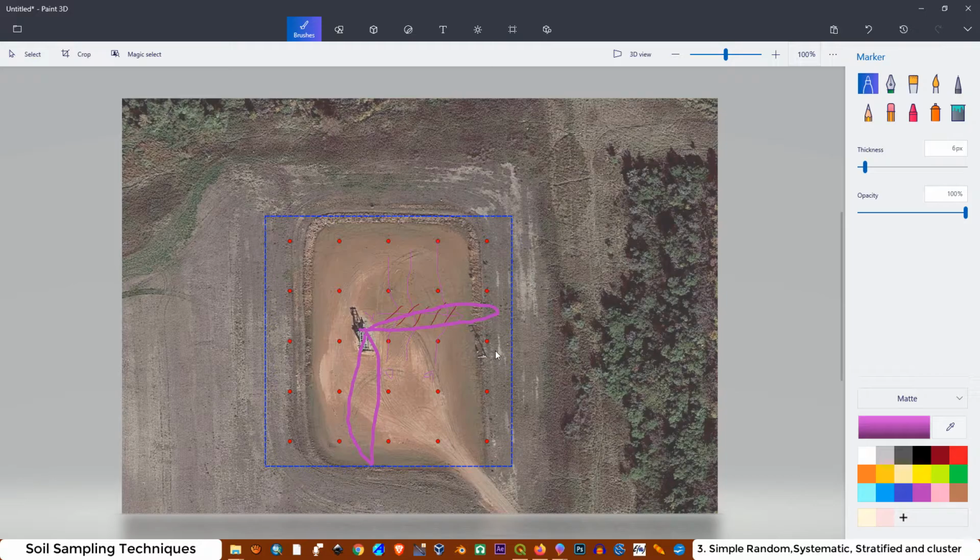Then, if we believe there is a pattern in our contamination, and then we cannot use the systematic sampling technique, and also we want to avoid the clusters from the simple random sampling technique, what other options do we have in order to cover all the extension? Then in that case we can use the stratified sampling. In this sampling technique, the population is broken into non-overlapping groups. Those groups are known as strata. Then a sample from each group is taken.